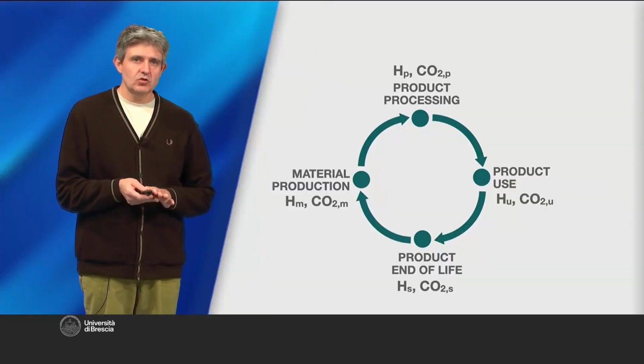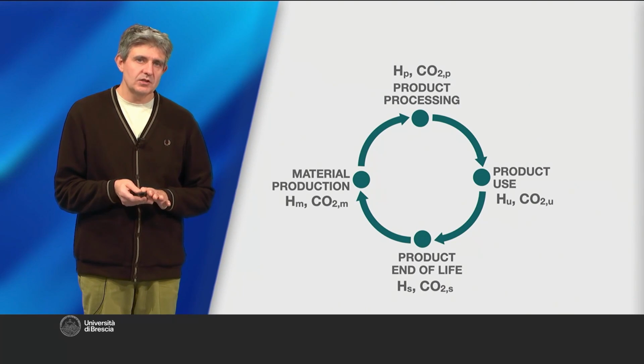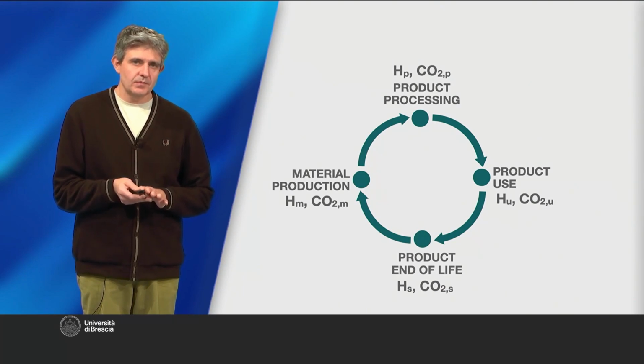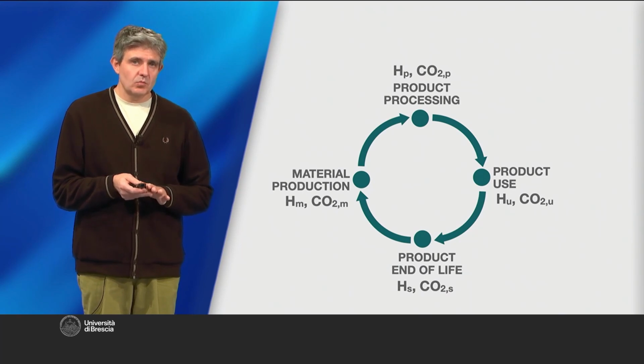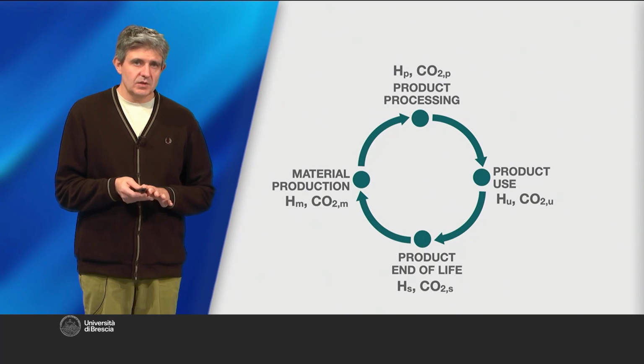The formulation of these new performance indexes is therefore relatively straightforward. However, it is not always easy to find information related to the embodied energy of the material or its CO2 footprint. Moreover, accurate design should take into account the entire life cycle of the product, from its production phases to its final disposal. This means making the design process more complex, but even in this case, there are material selection strategies that actually integrate with this type of design.